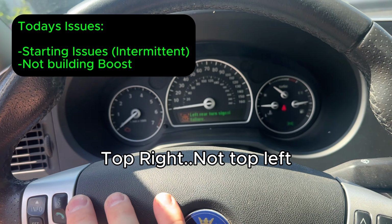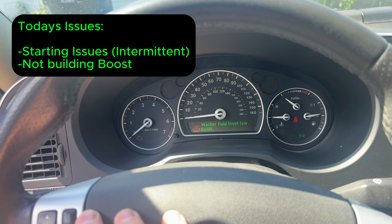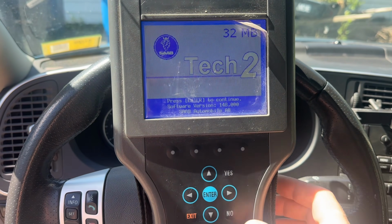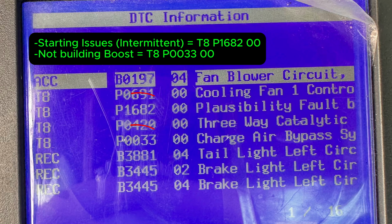Right now, the car has intermittent starting issues. It just kind of sits there and cranks sometimes. The other issue is that we're not building any significant boost. So let's plug in the Tech 2, pull codes, and get started. Perfect. Looks like we have a couple of simple codes. Today we will be solving P1682 and P0033.